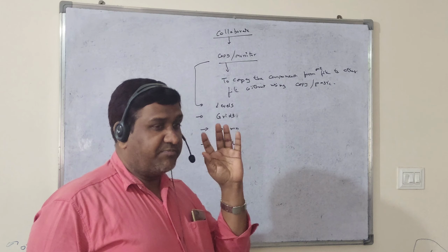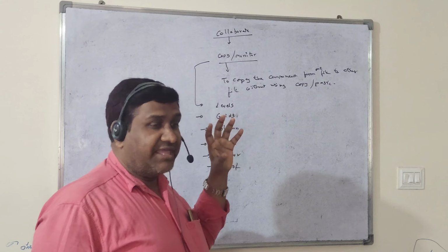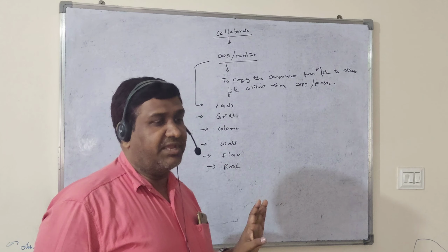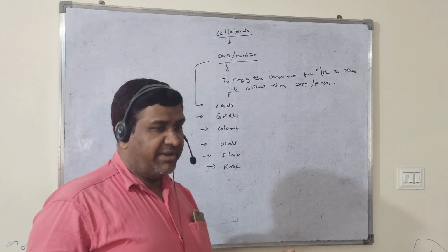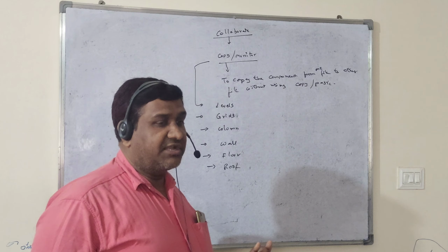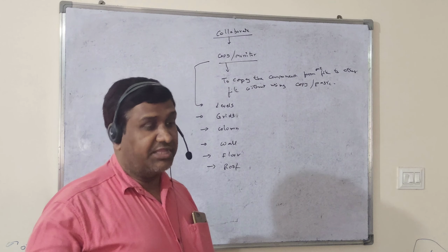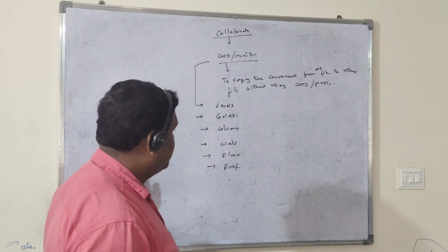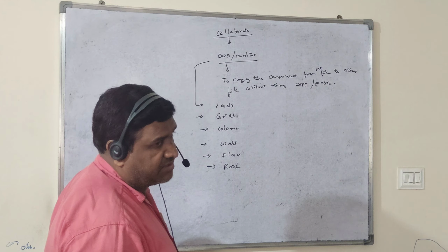With the help of that process, we can take the component from exactly the same location. It becomes a carbon copy, the same size, same view, same material, everything as a carbon copy. It is going to come into another file, from one project file to another project file. With the help of this we can do it here, the Copy Monitor.